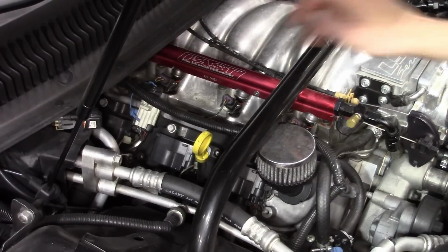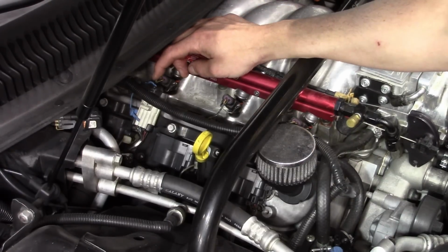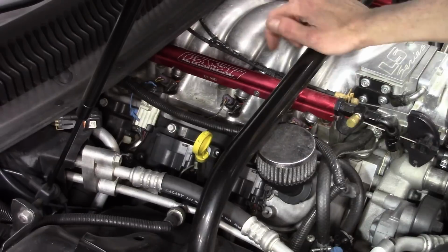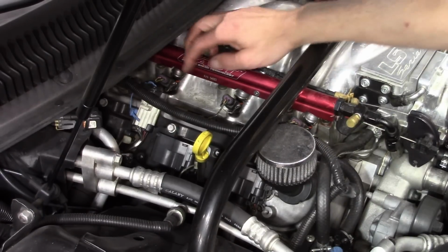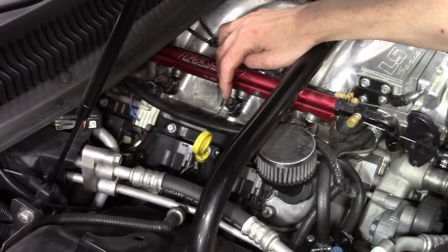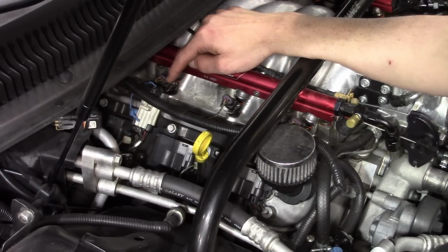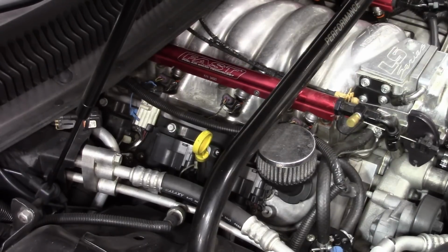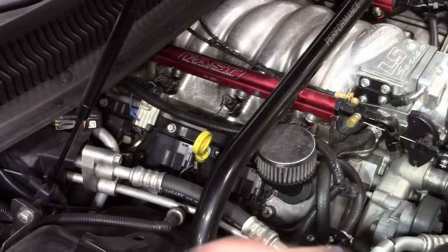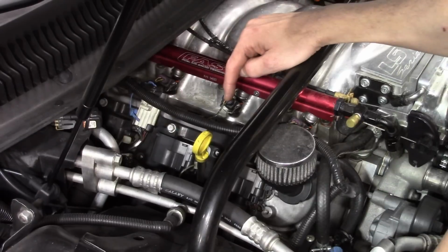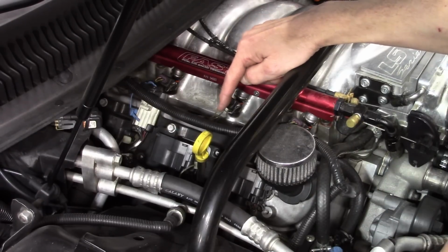And I'm going to cheat just a little bit here. We see there is kind of a brown, maybe yellowish wire. This car's really like 20-something years old. It's probably why I got that voltage drop on the lights. But we've got, I guess it's a brown wire here, brown wire here, brown wire here. However, the second wire is different on each injector. That's telling me, because this is ground side controlled, the same colored wire is going to be a power feed. It's the same power feed to each injector, and the other wire is going to be the ground side control.